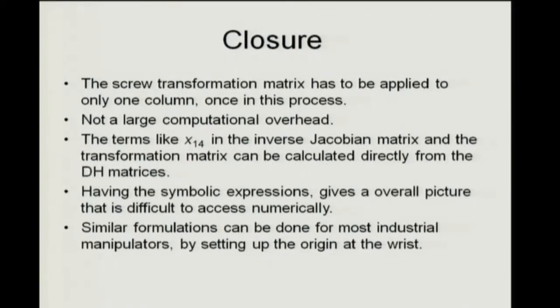And the second thing is, having symbolic expressions gives the overall picture that is difficult to assess numerically. So for example, you know right now that if your sin theta 3 is going to 0, you are going to lose out on this motion. So even if you are not using this explicitly, you have this knowledge about the manipulator.